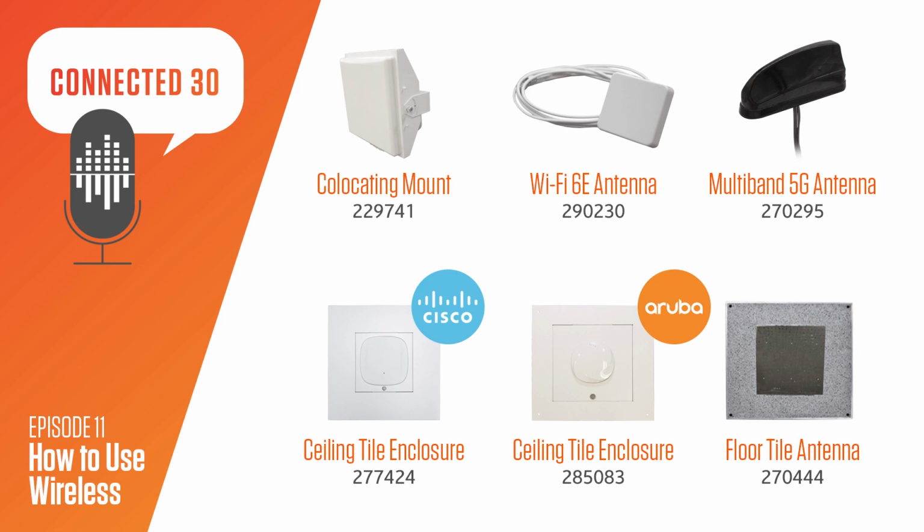Now, I mentioned a little bit about some of our antennas that are currently 6E capable. I want to talk a little more specifically about some of our antennas. We have what we call our small form factor line of antennas. Basically, these are antennas that we've been constantly improving, trying to think outside the box to make them smaller and smaller. Our original 6 dBi antenna design, for instance, was pretty much a 9 by 9 inch form factor as far as the radome, or the footprint of the antenna.